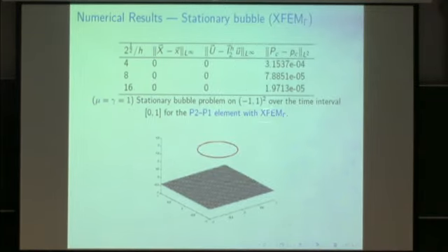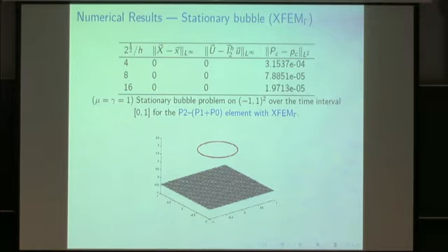And this is now with XFEM, so now I plot here the continuous part of the pressure, which would be exactly 0, and this is the coefficient of the characteristic function of the interface. Really, I should have plotted a cylinder here, but it was nicer to see it like that, and then you see that you recover exactly the stationary solution. You know that a circular interface should just be stationary, not move, and that's exactly what happens, no matter what you take for the pressure.